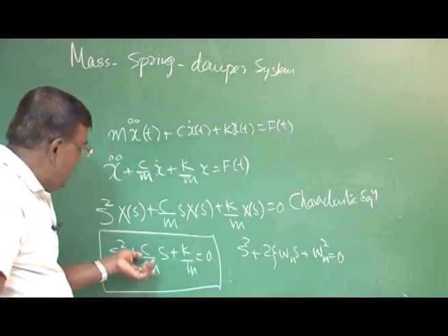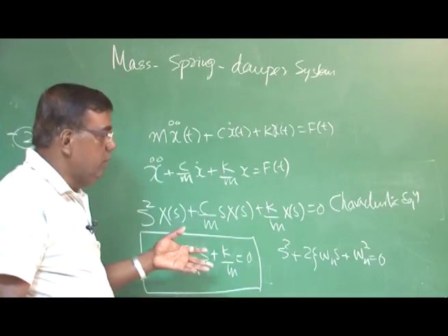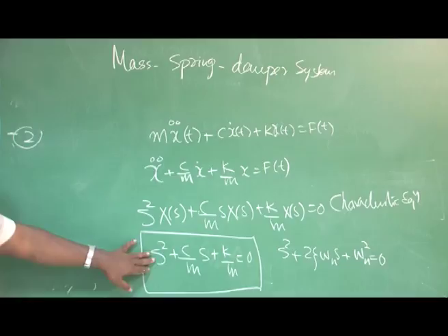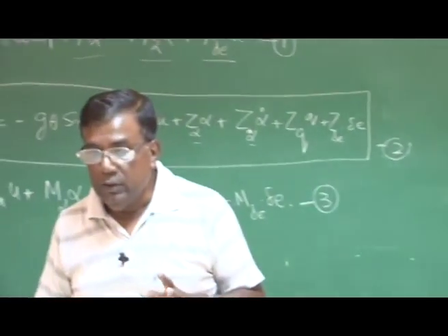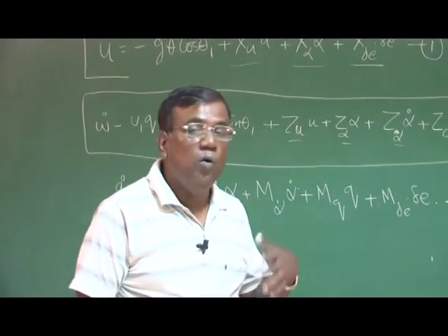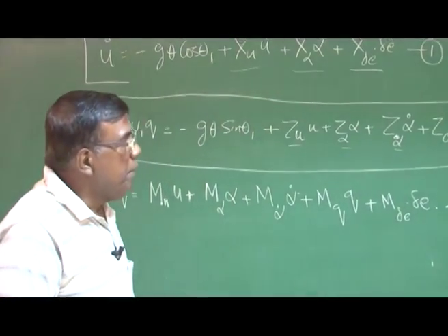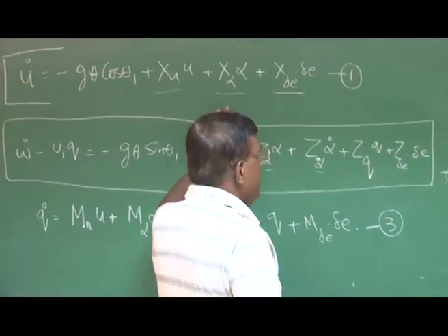So you can decide the value of c and m, k and m to design your system, because this also gives you a condition how do you adjust value of c, k and m so that it belongs to maybe a critically damped case, maybe an over damped case, maybe an under damped case, right? Similar approach also will be applying here.